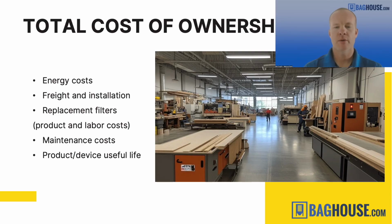But there's a few things that we can do to look at energy costs. One is putting a VFD or a variable frequency drive on your fan. And what that does is, even though your fan may be rated for the total CFM or volume requirement of your shop, if you happen to be not using half your pickups and those blast gates are closed, the VFD can lower the speed of your fan so it maintains velocity without pulling the same amount of air volume and essentially uses less power during that time period. So that's an important way to save energy costs.